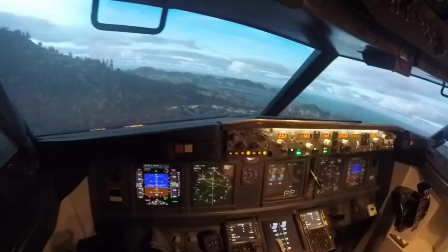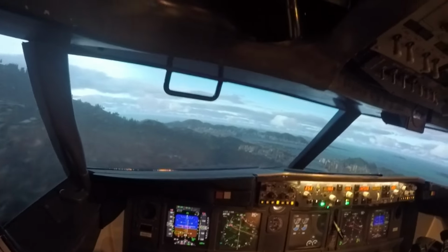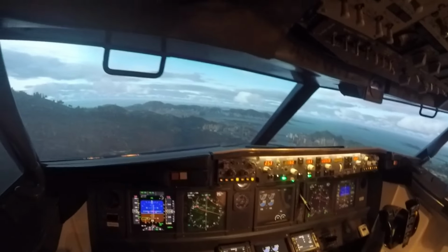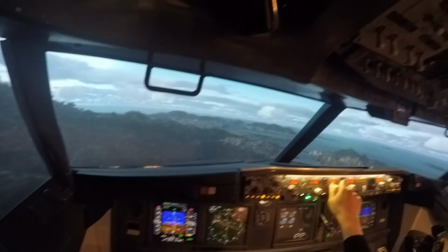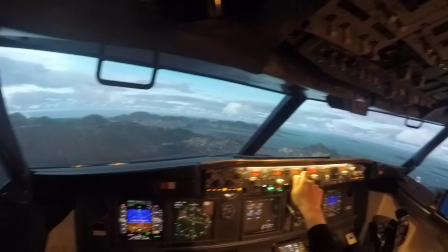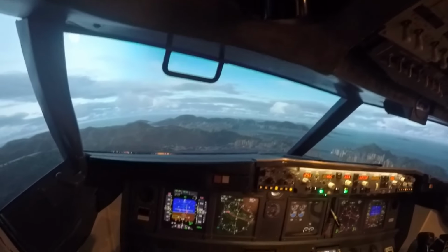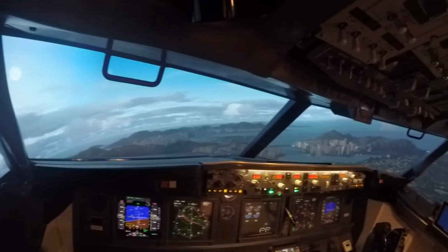And we'll just arm our speed brakes. Taxi, runway turn-off lights and landing lights are on. 500. And we'll just set our heading onto final, which is 253. And we'll start executing our turn.